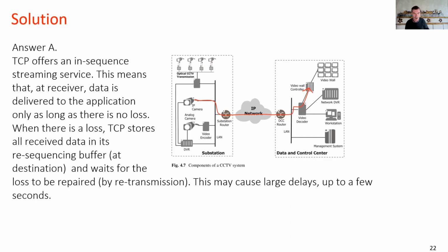As when we move to IP, we have the choice of using UDP or TCP. If we use TCP, we have this head-of-the-line blocking, which is why many applications that have real-time requirements use UDP. So PMUs, when they stream to the PDC, will typically use UDP. And of course, you will need a mechanism to detect losses. So you will typically put an application layer acknowledgement and retransmit at the application layer, where you can benefit from doing it at the application layer.